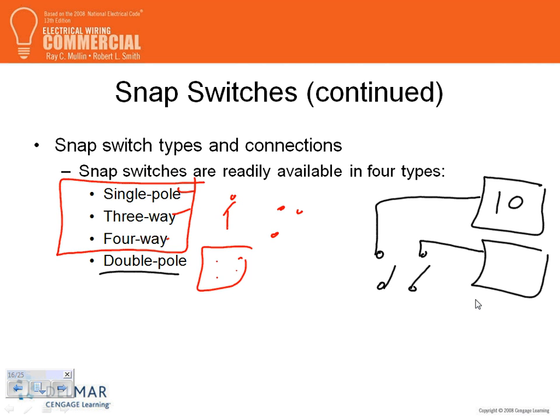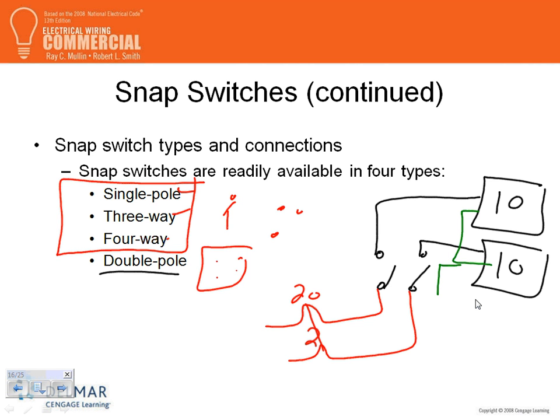So I have 10 lights here and 10 lights here, 2 circuits, and they're sharing a neutral. And each one of these circuits is coming from a 20 amp. Here's another 20 amp, tied together because they're sharing a neutral. This is a great application for a 2-pole switch, where with one hit, Brad, you can turn 2 circuits off. 2 circuits. That's where the 2-pole is. If it's 1 circuit, it will be a waste of money. That's a great application if you want to do this.